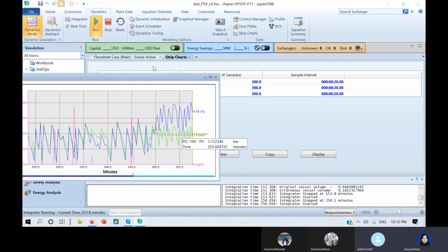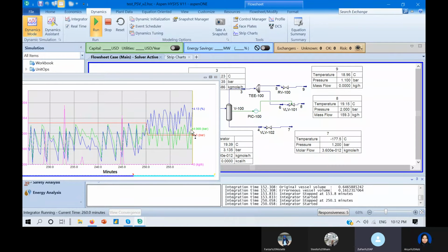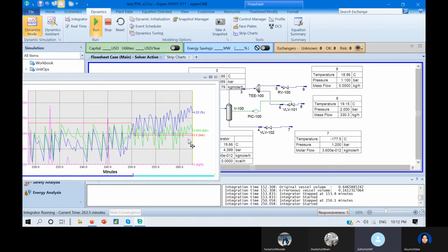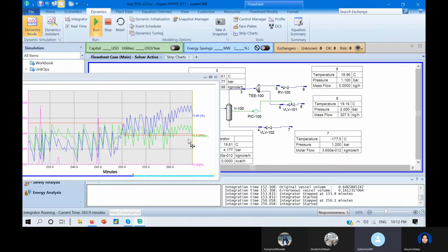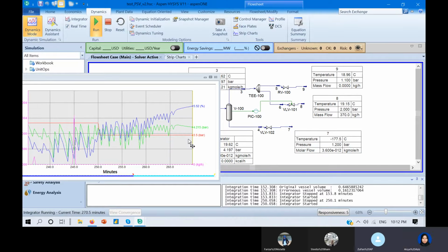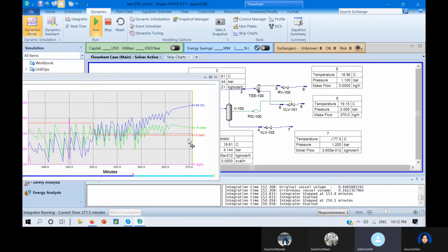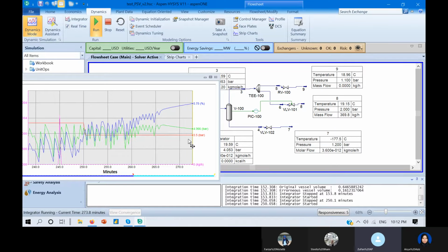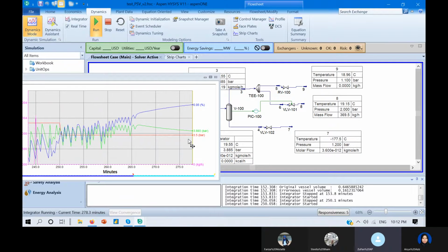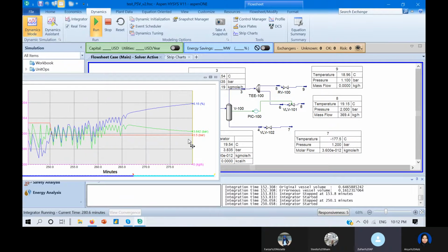So it's now a bit unstable. Let's wait for a moment. The idea of a PSV is to protect the vessel. We have a pressure control valve, that VLV 101, which just controls the pressure at the set point that we want. It doesn't protect the vessel, and it is also not meant to protect the vessel.